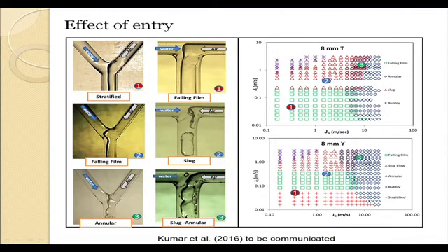Well, now if we come back to our entry section, once we have understood gas liquid downflow through millimeter size channels, we find that at low velocities we observe falling film flow for quite a good range of velocities. Same experiments with the same diameter tube we have performed for the same flow velocities, just we have changed the injection system. Instead of introducing the two fluids from diametrically opposite points, this time we try to insert them at an angle to each other. And what do we find in this particular case?